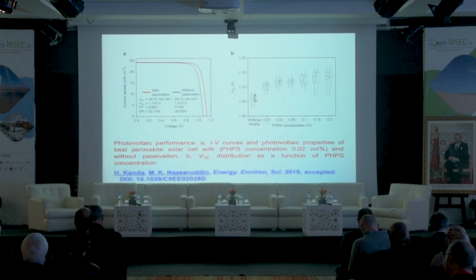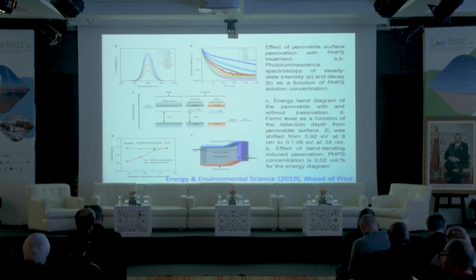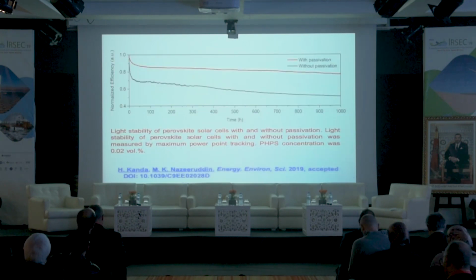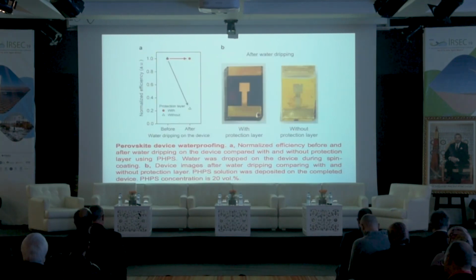So this is the IV characteristics, 22.1% efficiency with the passivating agent, and without it you have 20.5% efficiency. These are some other characterization techniques to prove that this is passivating, and you can see the increased luminescence intensity, and the carrier lifetime is also increasing by putting in this passivating agent. It also gives you enhanced stability as shown here. This is with the passivating silicon dioxide, and this is without a passivating agent. So this enhances the stability as well.